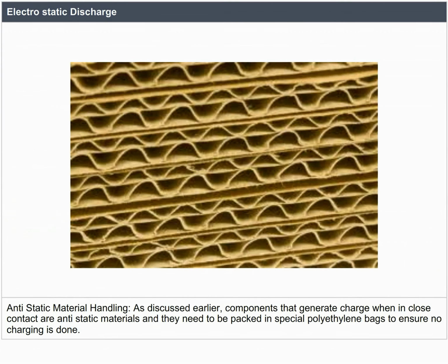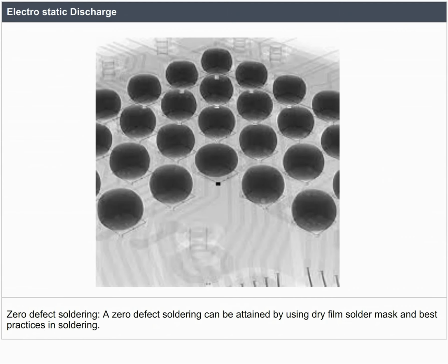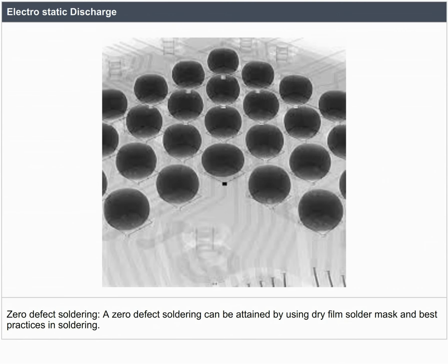Anti-static material handling. As discussed earlier, components that generate charge when in close contact are anti-static materials, and they need to be packed in special polyethylene bags to ensure no charging is done. Zero defect soldering. A zero defect soldering can be attained by using dry film solder mask and best practices in soldering.